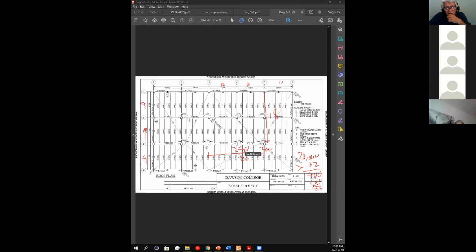You understand? In other words, between here and here, what would this one be? Now, this one here can be slightly different because I believe that this is only 18, right? In other words, this is 18, and in this direction it's only 10. So 18,000 times 0.02 would be 360, right? 360 plus 100. So this one would be at 460 instead of 500. You can make it a little bit less. But if you want, make it 500, as long as you have 2%.